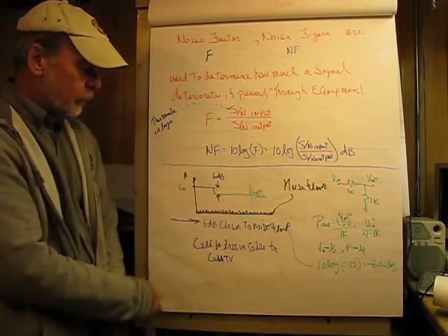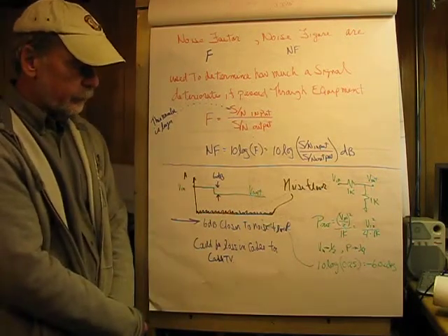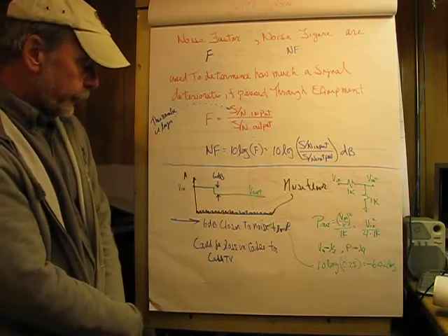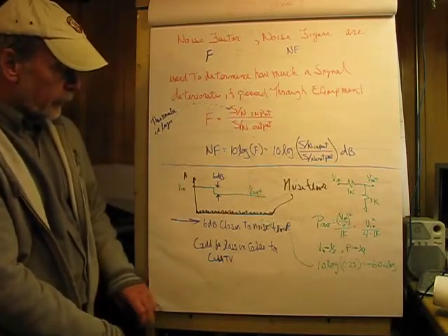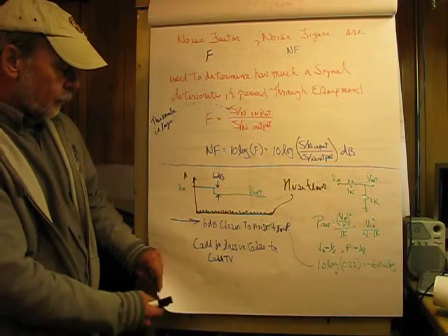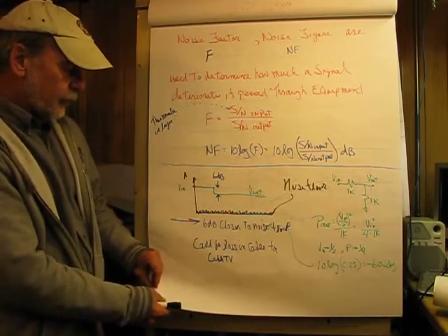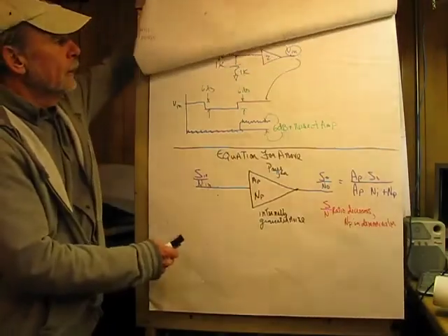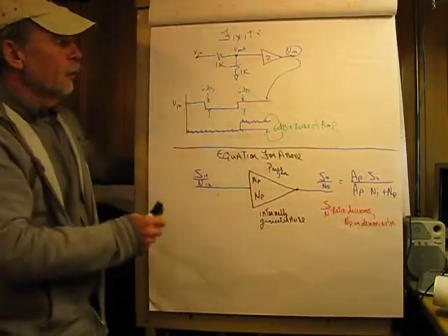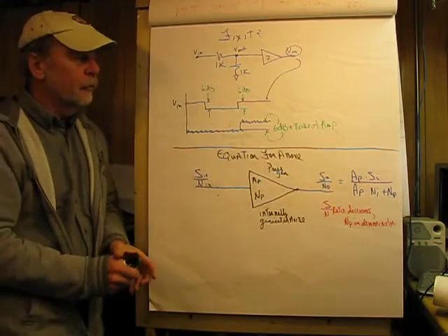You might be thinking, well, that's okay, I'm just going to go through and add a ×2 amplifier and fix it, and that's what we're going to look at doing here. So I lost some voltage and compromised my signal to noise ratio. When I say lost voltage, I also lost signal power too.